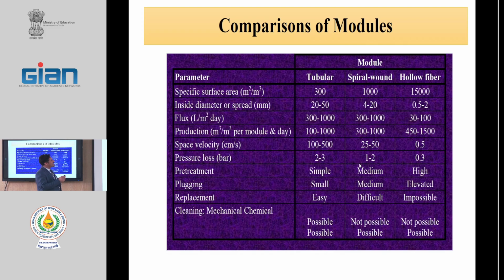But I say that hollow fiber membranes are only used as low pressure gas separation, microfiltration, and ultrafiltration membranes. Hollow fiber membranes cannot be produced for RO. 50 years ago, some companies fabricated reverse osmosis hollow fiber membranes, produced hollow fiber membrane and coated a polyamide layer on it, and built a factory in Kuwait.